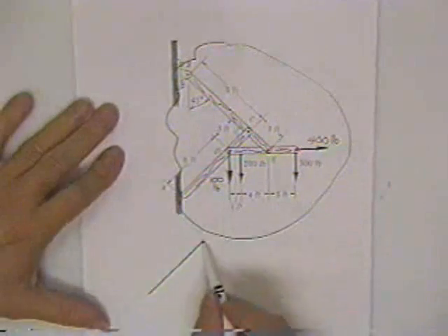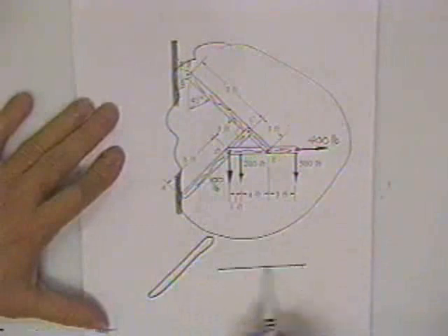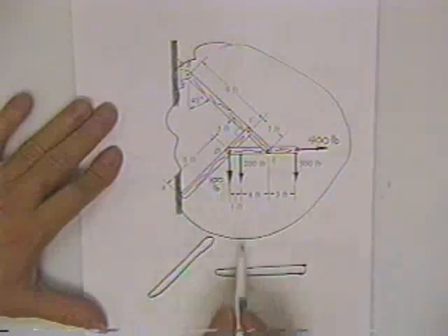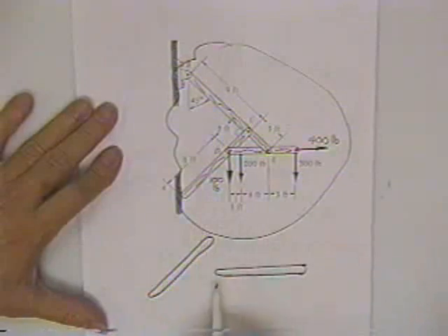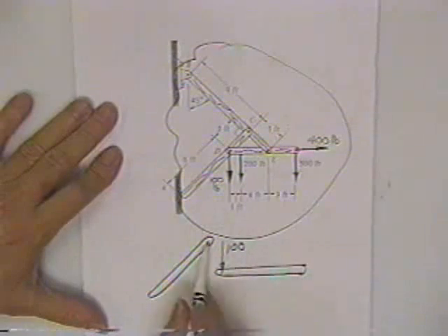But when you draw this free body, that's this one, and when you draw this free body, you've got to pick a place, just like a contractor. Contractor has to literally go put that 100-pound force on this member, or he's got to put it on that member. It doesn't make any difference. But if you put the 100 on this one, for heaven's sakes, don't also put the 100 on that one.